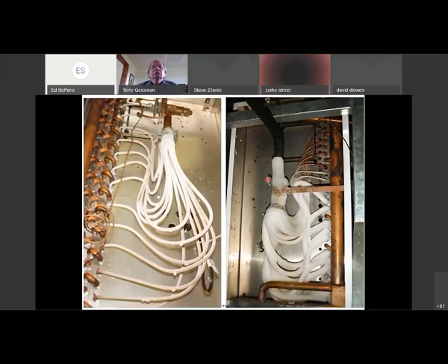So preferably, I like to see where the distributor is in the vertical position, right, where the liquid refrigerant leaving the expansion valve actually comes down in the vertical plane, so that it feeds all the distributor tubes evenly. Okay, pretty much the same thing with what you see here. However, you do see some of the distributor nozzles or tubes here. Some of them are feeding and some of them are not, and that could be because of the way you have this set up.